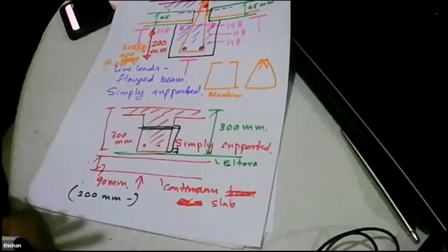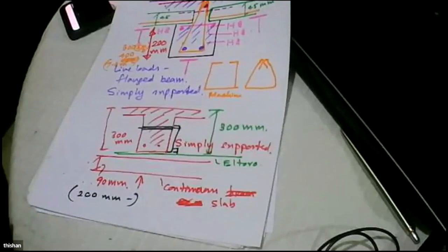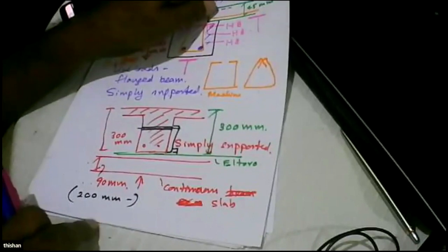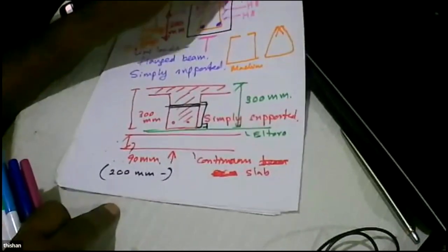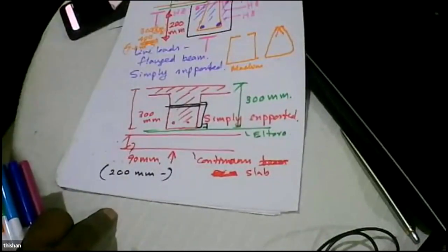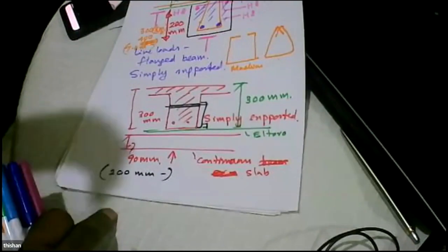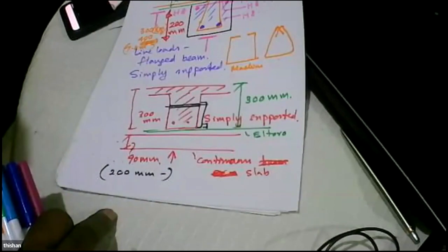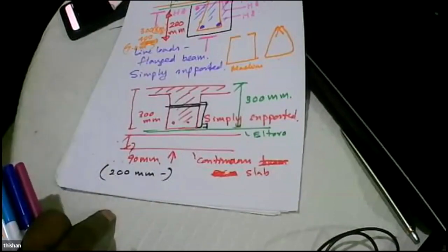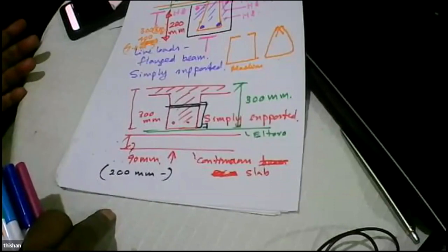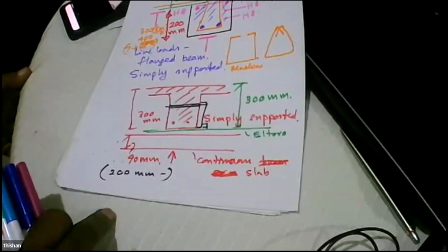Even if you complete a 150 slab, then you apply the leveling screed, then you do tiling. So once you consider all that, it comes to about 200 millimeters. So the cost penalty for using this is the building will be taller by 100 millimeters if you are going for a ceiling. If you are not going for a ceiling, no problem. The beams are seen.